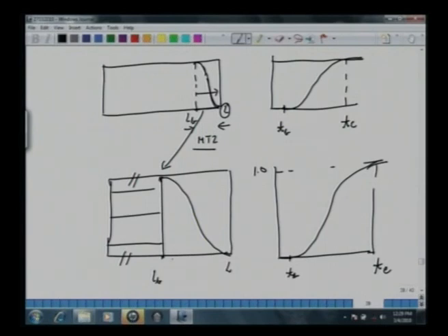All right, so if you choose this constant level here, this distance here, then this is the level of concentration here. If you choose here, that means this bed is partially active, it's partially saturated, it has to reach 1. So one can say that this shaded region here represents the region which is unspent or fresh adsorbent. This is a region which we can say is partially saturated.